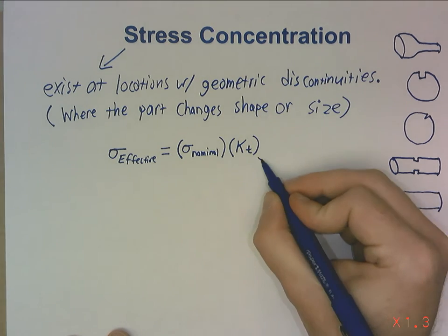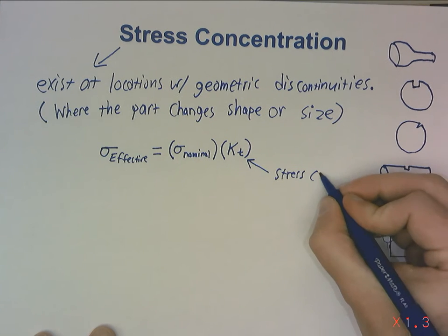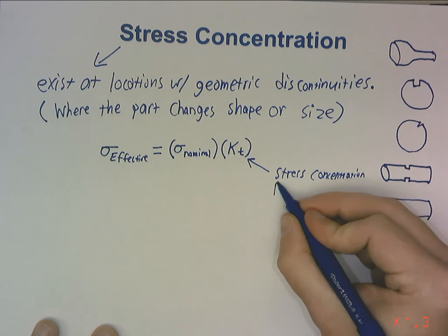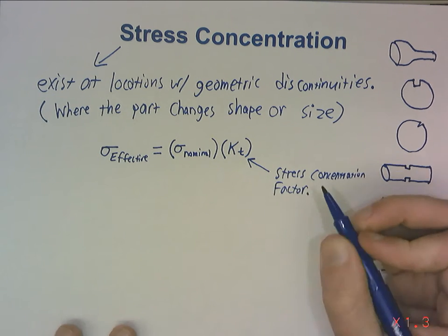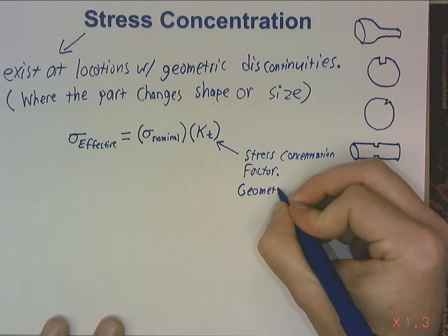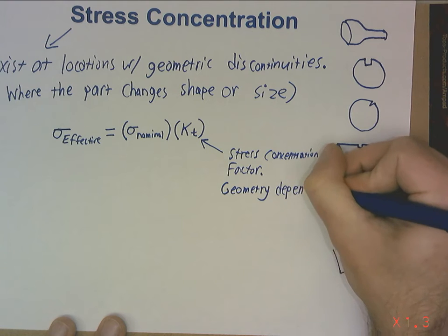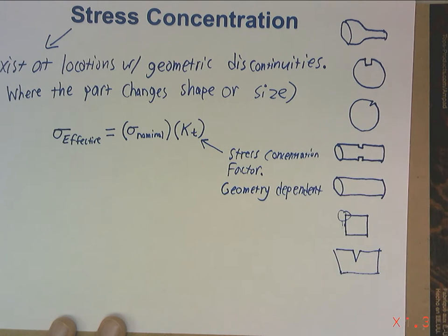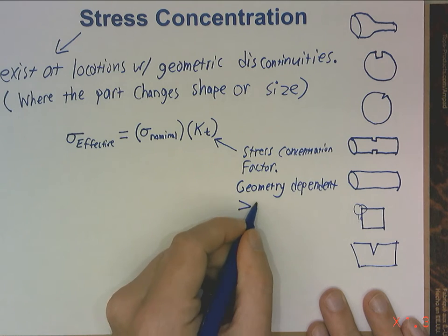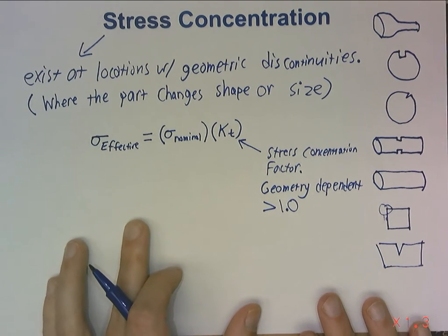This is going to be a stress concentration factor. It is geometry dependent, and it's always going to be greater than 1 for any real stress concentration.